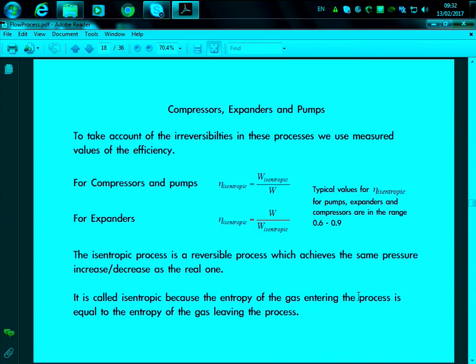Why will it make the process irreversible? The efficiency. Here we are assuming that this doesn't have any efficiency involved into it. So it's 100% efficient. We can go forward or backward without losing any efficiency. That's why we say that it's isentropic. But we know that all processes have an efficiency, and it is very hard to have a 100% efficient process. So that's how we get the efficiency, and we can obtain the actual work.